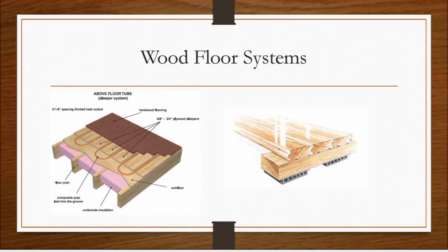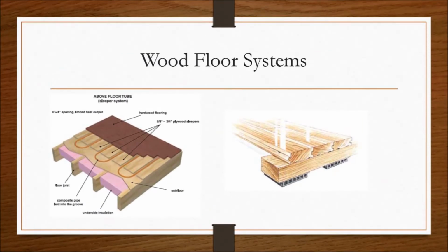Wood floor systems. In wood light frame construction, a floor usually consists of wood joists resting on a larger beam or load-bearing walls. A structural subfloor, such as plywood or steel decking, is laid across and secured to the joists.